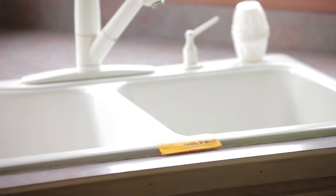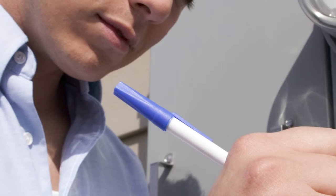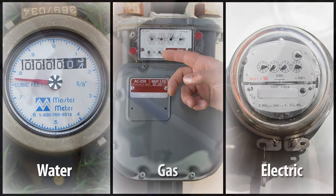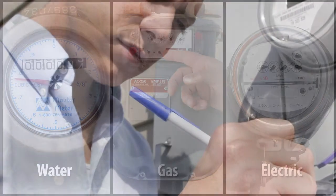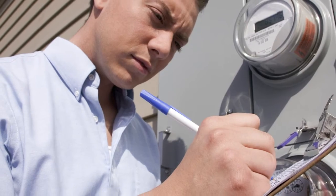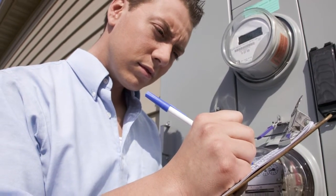Winterization stickers are to be placed on all winterized fixtures and valves. The final step when completing a winterization order is to take meter readings for water, gas, and electric. It is mandatory that these readings be reported when submitting the order completion. This is important information should the winterization ever become compromised.